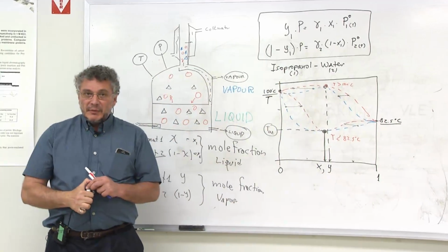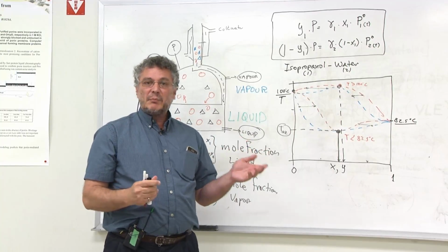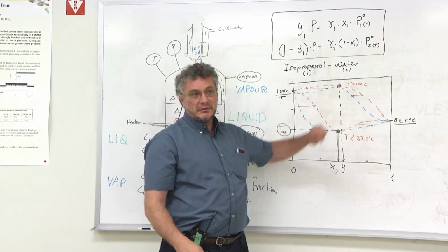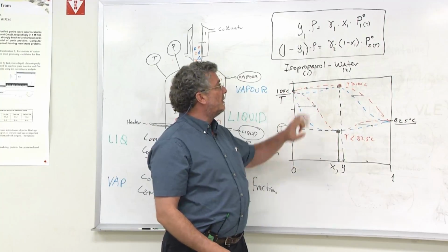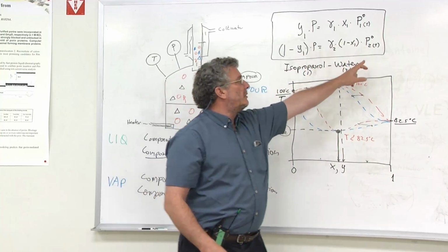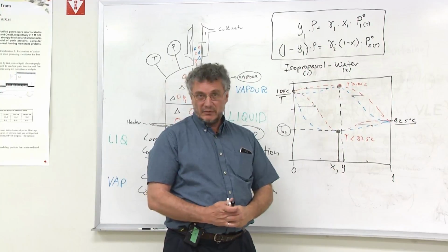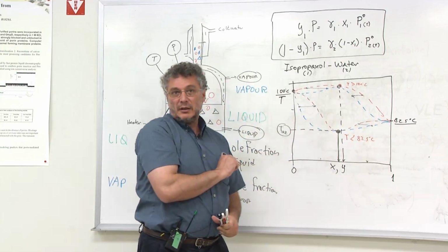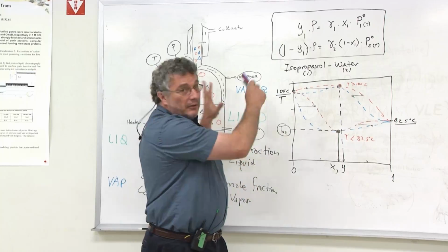So what you will determine with your experiment here is whether the isopropanol water system belongs to the minimum azeotrope or maximum azeotrope. And then you are going to use the values that you got, the triplet values of vapor composition, liquid composition, and temperature, to determine the interaction parameters of Van Laar by trying to fit these equations to your data. This is the theory behind the experiment.